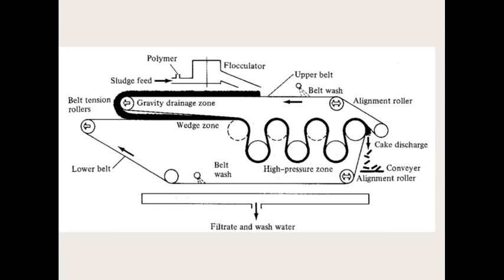More recently, the beneficial use of dewatered sludge and ash from sludge incineration has been developed. Nowadays incineration of sludge, or burning of sludge, is also done, and the residue ash we generate can be reused for various other processes. The more advanced methods of sludge or ash disposal are usually to reuse composted or digested sludge in agriculture as a fertilizer or in landscaping, or reuse it as a phosphorus or nitrogen source in agriculture as an additional fertilizer.